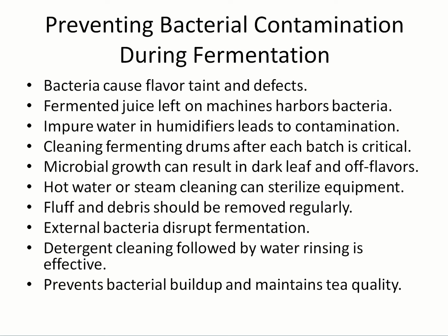During fermentation, bacteria cause flavor taint and defects. Fermented juice left on machines harbors bacteria. Impure water in humidifiers leads to contamination. Cleaning fermenting drums after each batch is critical. Microbial growth can result in dark leaf and off flavors.